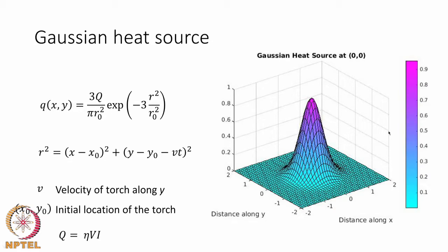And as you can see, we can actually mathematically represent the heat source that we have seen in the previous slide by using what is called a Gaussian function. So, the function itself is shown to you here, written exponentially in a form that goes as e raised to the power of minus x square, where x is the length, and in 2D you have not just one length, but you have it in the 2 directions.